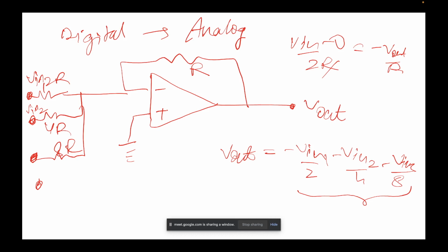Priyanka, you can just drop me an email and I'll reply during that. But the basic idea is that to convert digital to analog, you need an op amp in the negative feedback mode, and we provide a bunch of inputs on the left side. You can see that the inputs are here, V in 1, V in 2, and V in 3, and then, due to the adder configuration, we can add them up. That's how we convert digital to analog. Is it somewhat clear, Priyanka?